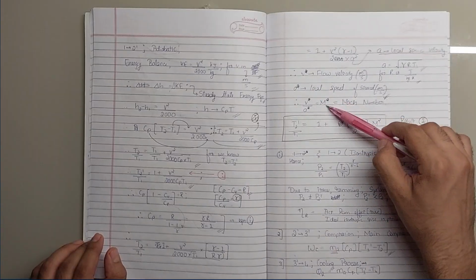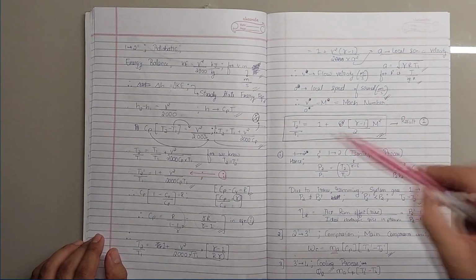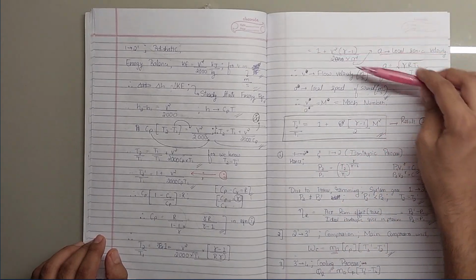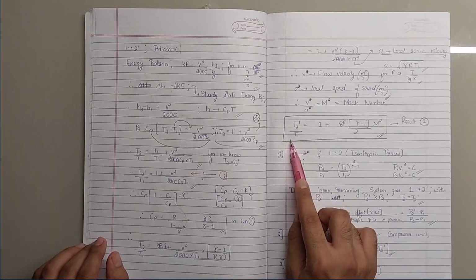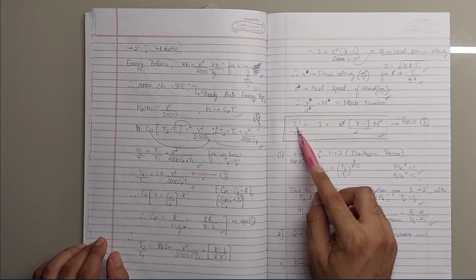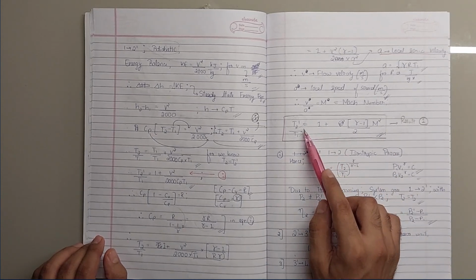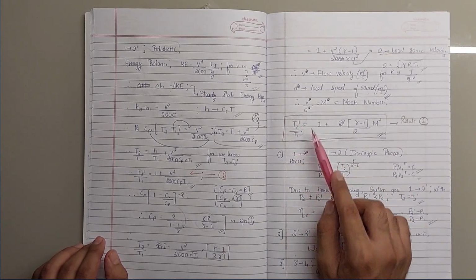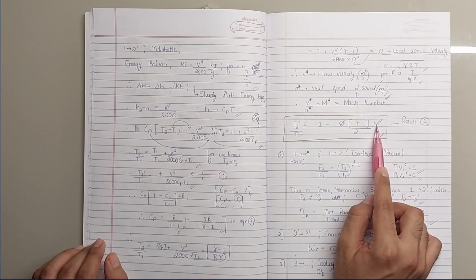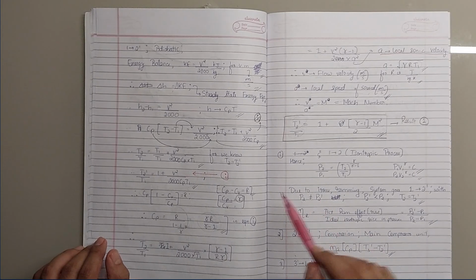We know Mach number is equal to the flow velocity of any fluid divided by the local speed of sound in the same medium. Therefore V by A equals Mach number, and V square by A square equals M square. So we get a relation between T2 dash upon T1. T2 dash is the stagnation temperature, T1 is the static temperature. We get a relation between these two temperatures equal to 1 plus gamma minus 1 by 2 into Mach number square. Mach number is the speed at which the aircraft is traveling.